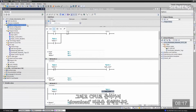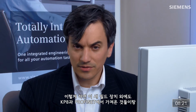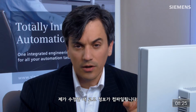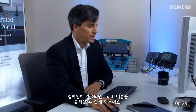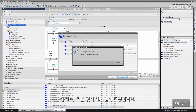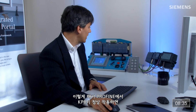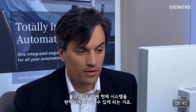Let me give focus to the CPU and click the download button. Now it's going to compile this new field device, the KP8, including what I put on Profinet, as well as all the new code changes I've made. Once it's finished compiling, then we can click the load button. Now it's going to load all that down to the system. And in fact, we should have a fully operational KP8 on Profinet and have full control over the current system in just a matter of seconds.